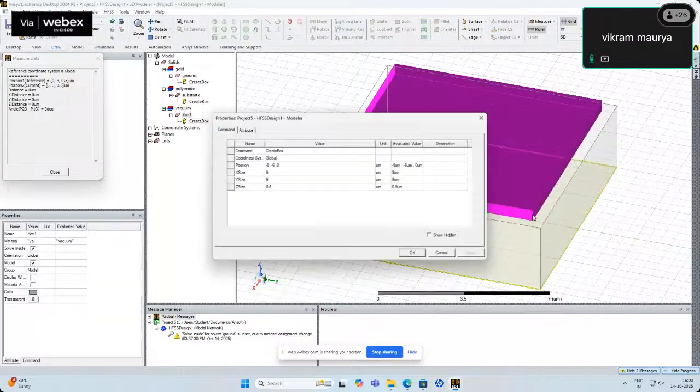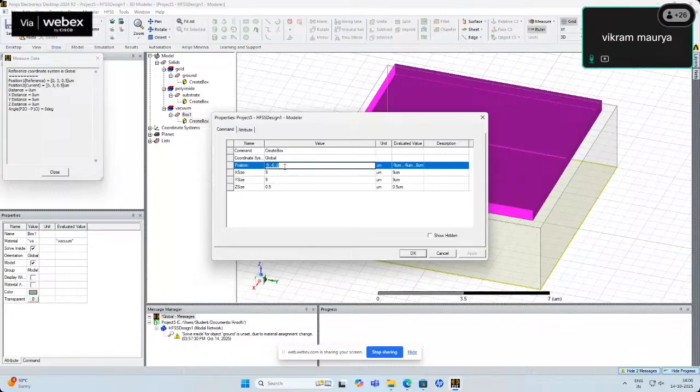We'll expand it and then give it a height, and then the dialog box appears. Okay, now this particular part is important to notice. First, we will assign PL, so this is patch length. Whatever I'm putting on the substrate or mounting on the substrate, I can say this is patch length, PL by 2. Again, now my starting point is simply TG plus TS.